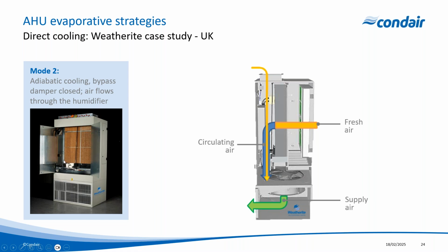Now for the evaporative system, it is a recirculating evaporative system. So if you look at the photo, we do have a small sump in the bottom there, and then we do have an individual or single pump that's used to pump water to the top of the media. We'll continually recirculate that, and then we'll periodically drain that out in order to maintain a specific water quality. And that really helps just to optimize the water efficiency of the evaporative system itself. So you can see overall, just a very simple system.